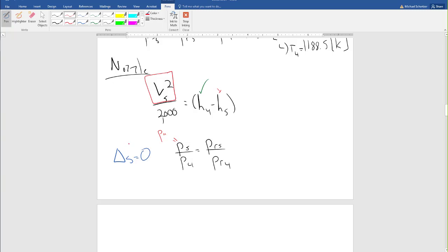Sometimes it'll tell me that, sometimes it won't. But if we remember, right, here's the diffuser, then there's some stuff up here. Here's the nozzle, right? This is state 5, this is state A. The states that touch the atmosphere are always the same in terms of pressure, right? So the temperatures are different, right? This temperature is going to be a lot hotter than the inlet temperature, but the pressures are the same, right?